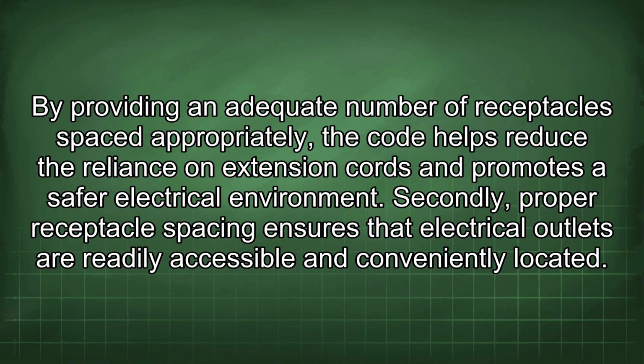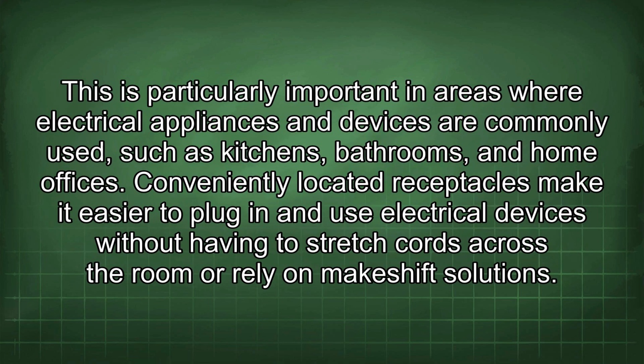a safer electrical environment. Secondly, proper receptacle spacing ensures that electrical outlets are readily accessible and conveniently located. This is particularly important in areas where electrical appliances and devices are commonly used, such as kitchens, bathrooms, and home offices. Conveniently located receptacles make it easier to plug in and use electrical devices without having to stretch cords across the room or rely on makeshift solutions.